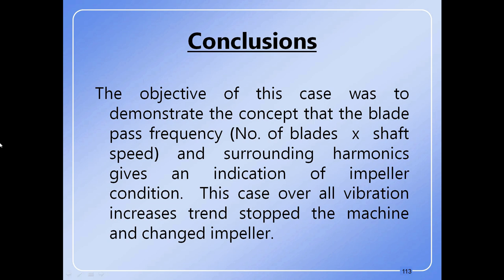In this case, the overall vibration increase trend spotted the machine problem, and after the change, the vibration signature of the pump took on a new shape without high amplitudes, and the blade pass frequency and the overall vibration level returned to normal.